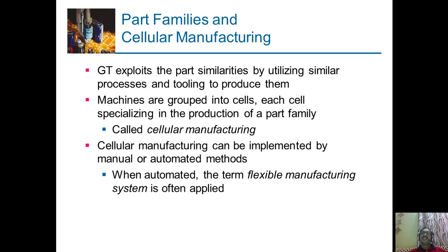then what happens? This group of jobs will come to these 3 machines only, and not move to the other lathe machines. But if all 10 lathe machines are placed randomly, and jobs are coming in, then material movement may increase. And if this material movement increases, then non-machining time increases.